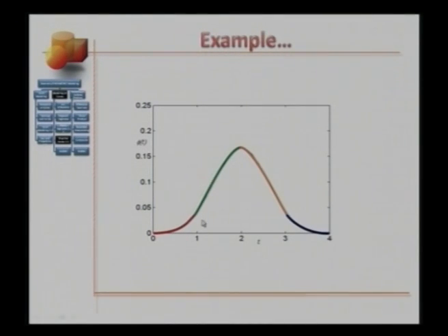What do you have to say about the continuity conditions at these 3 junction points? You're right. The position, slope, and the second derivative are continuous here. It's continuous here, and the 3 are continuous here, which would make this basis function a C2 continuous basis function throughout the span of t. In the sense, for t going from minus infinity to plus infinity, this will be C2 continuous throughout.